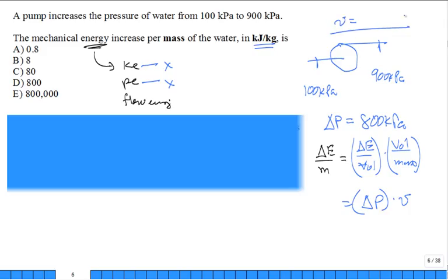Somebody says, I need a textbook to tell me that. No, you don't. Give it to me. 0.001 meters cubed per kilogram, isn't it? If I have one liter of water, that's 0.001 meter cubed. There's 1,000 liters in a cubic meter of water. It's 1,000 liters per cubic meter, true. And 1 liter is 1 kilogram. I can remember that. Okay, so the specific volume of liquid water.